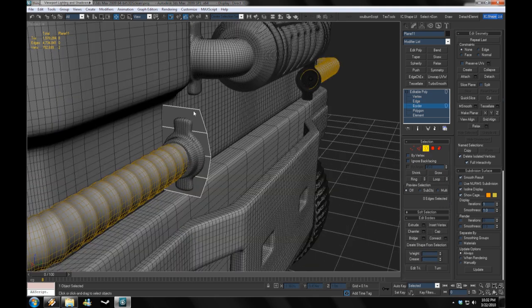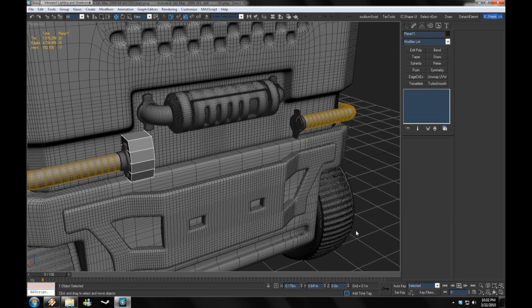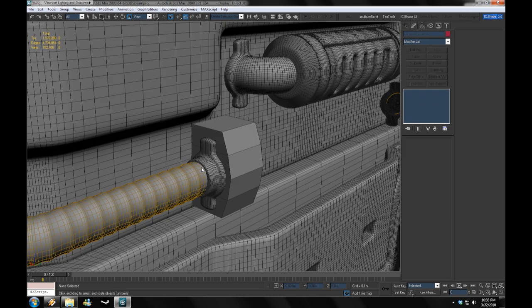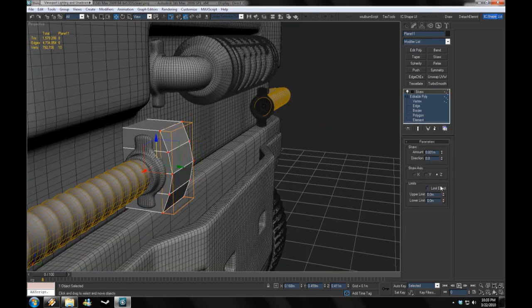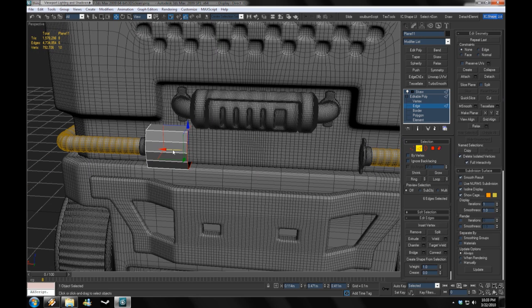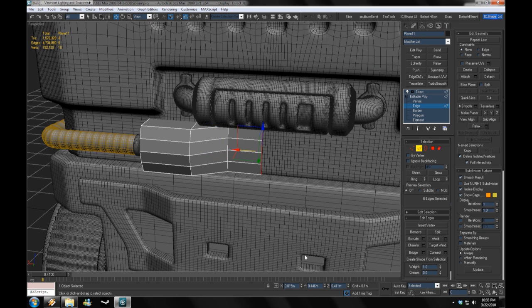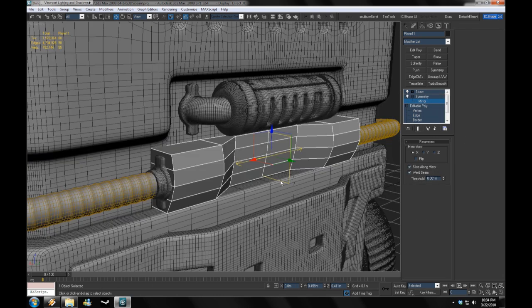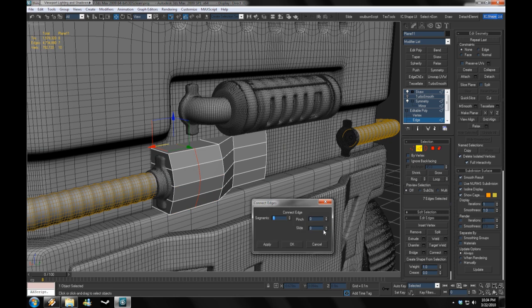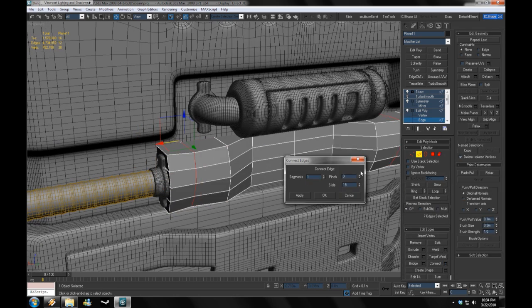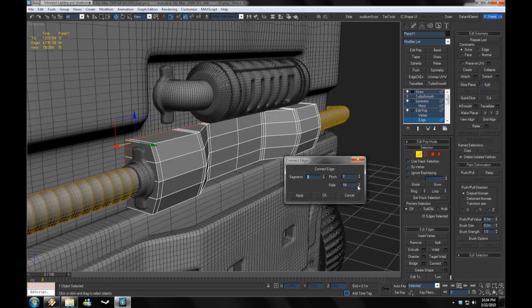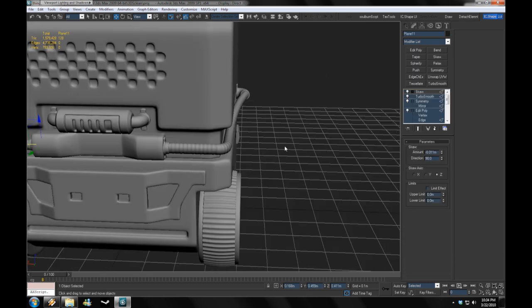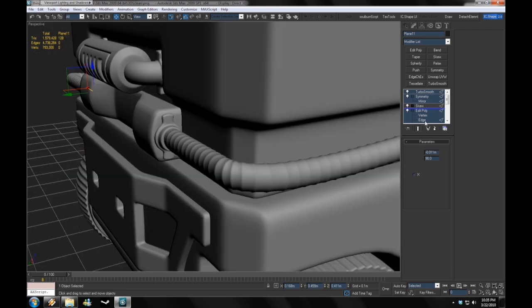Right, so now I've just started to define this kind of back fuel converter type shape. I don't know what you'd call it. I'm just making up names for it so it sounds like it has a function. So I've made it kind of round and I'm giving it skew here so it doesn't look so bland and round. And again, I used shift drag to make shapes very easily. That's probably the best tool in the entire Max tool set, is shift drag. And for some reason, my skew modifier is acting up, so I just redid it real quick. Or at least I'm redoing it now, rather.